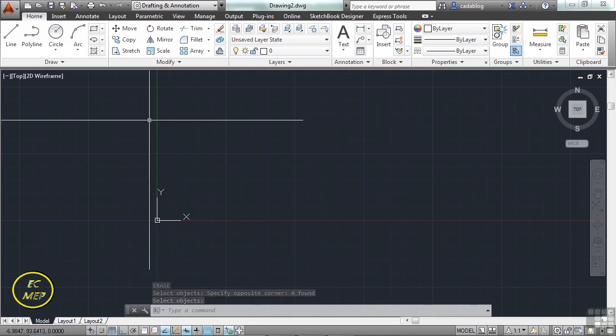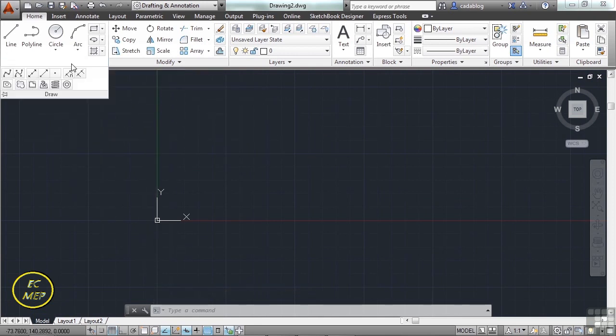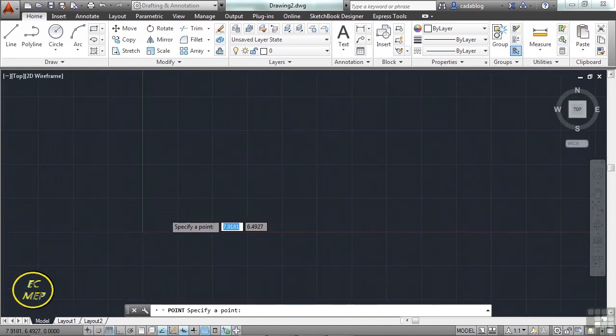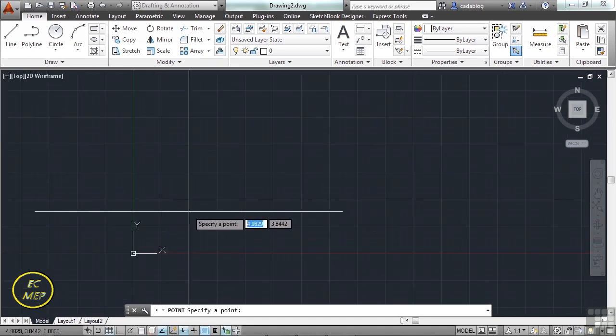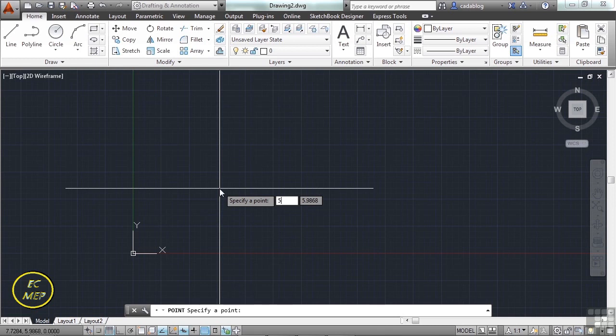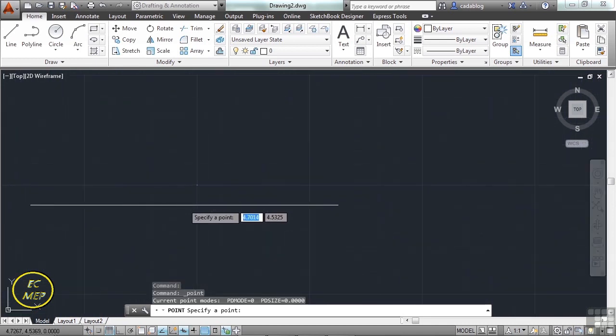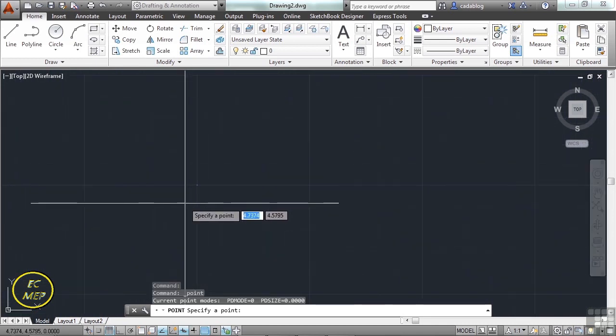Now let's put a point in at a specific coordinate. Start the point command, and then let's zoom down here a little bit. So type in the number 5, the Tab key, and the 5. So this will put us at coordinate 5,5, right here. Points are also three-dimensional, but not in AutoCAD LT, just like every object in AutoCAD. If you leave the third coordinate off, it will be drawn at an elevation of 0.